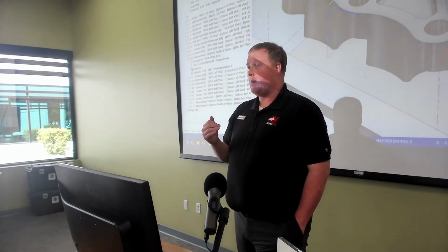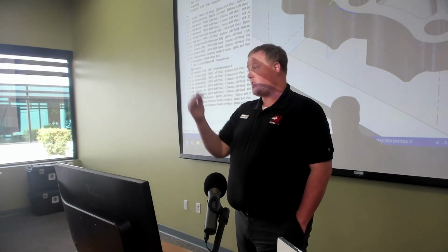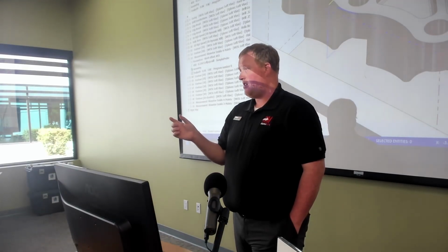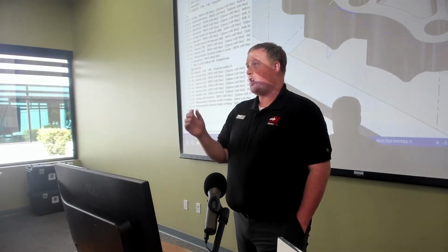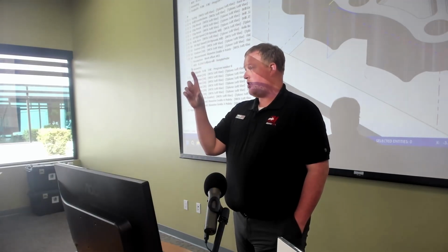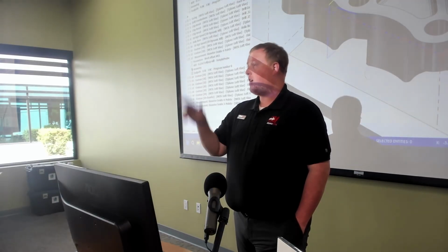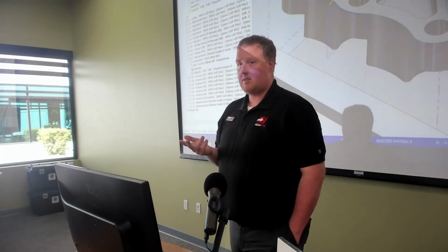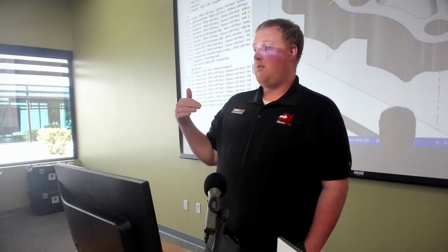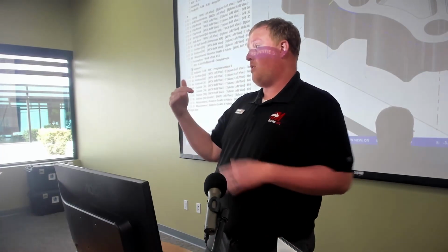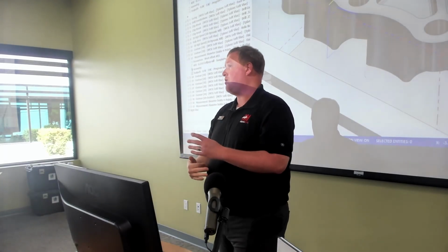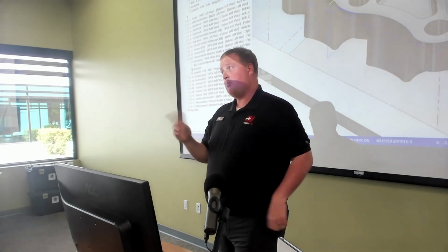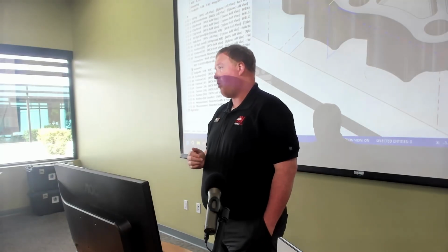If it's dull, are we talking length or diameter? Well, just the length. On length, it knows what the nominal should be, and based on what it measured, there's usually a tolerance associated to say, did it break because we're measuring too short, or it pulled out and we're measuring too long now. So usually it's just a simple in or out of tolerance, more or less.